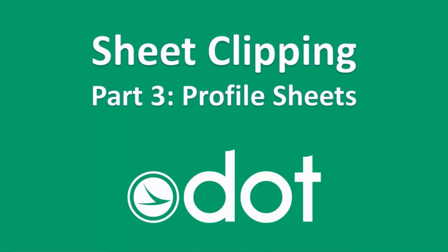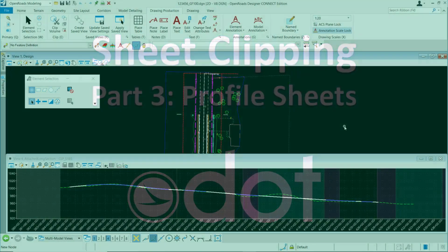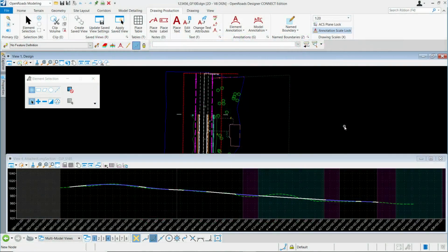In this video, we'll take a look at generating some profile-only sheets using the ODOT CAD standards for OpenRoads Designer. I already have a container file with my references attached and my profile displayed. The references I need for generating a profile are my alignment itself, which also contains my proposed profile, and the file that has my terrain model. Once those are attached, I set the terrain active, which gives me my existing ground.